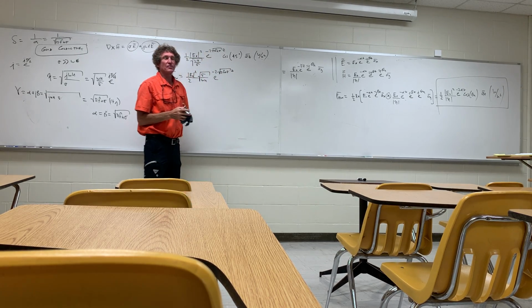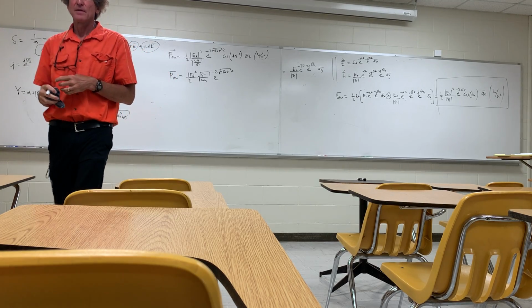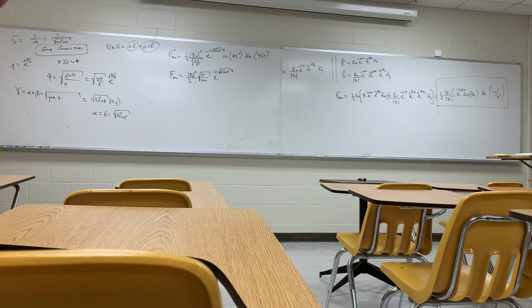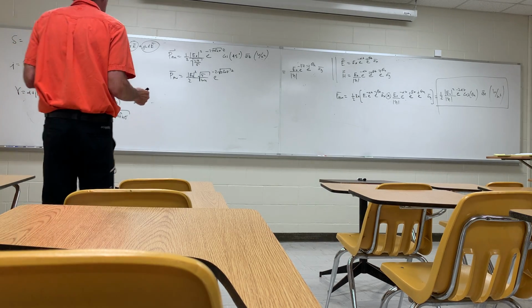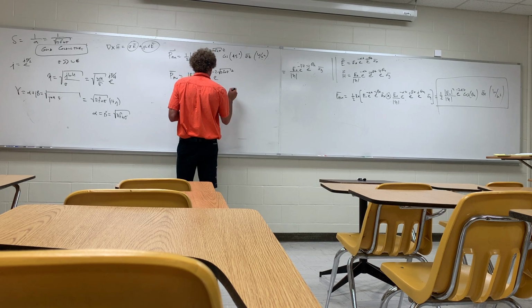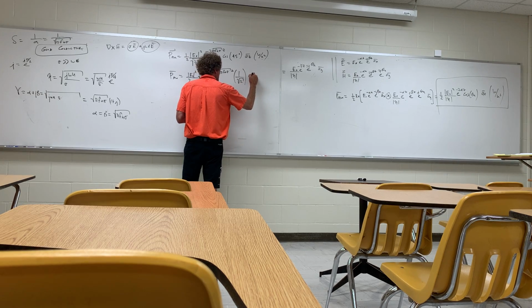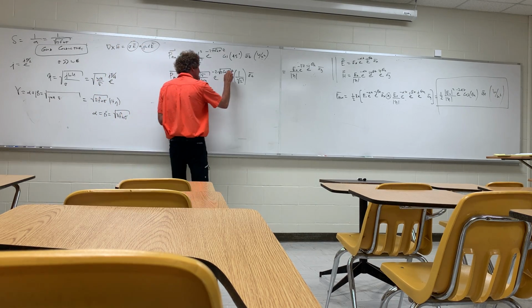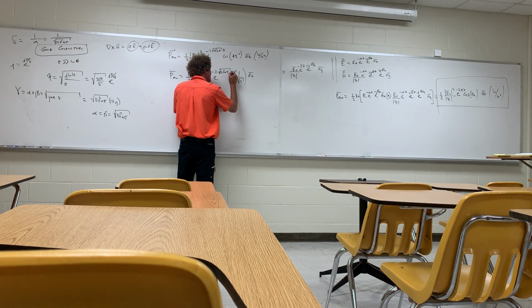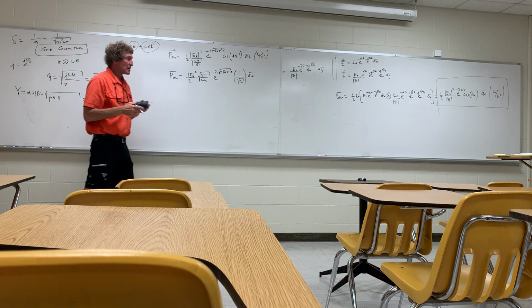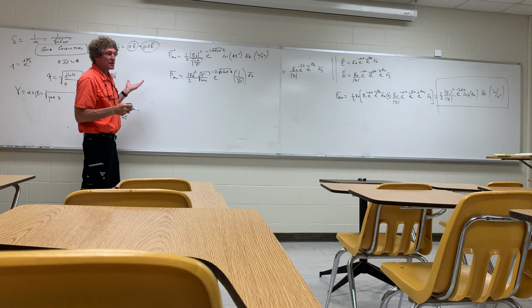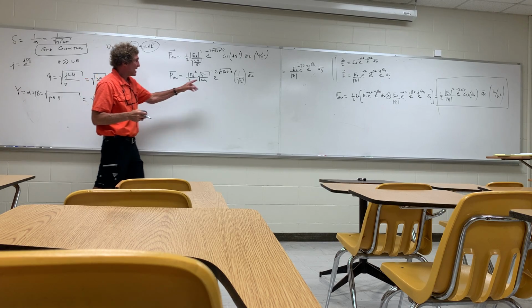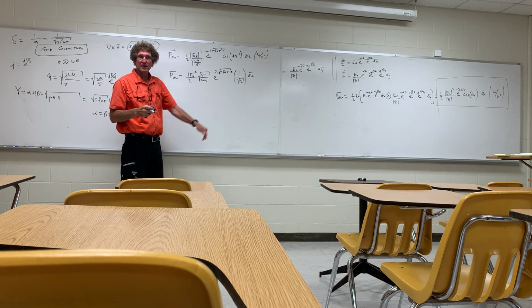And what is the cosine of 45 degrees mathematically? 1 over the square root of 2, that's a good way to write it. So I can simply take this thing and put this times 1 over the square root of 2 in the a_z direction. And that's power flow in a good conductor if it's flowing in the z direction. Now that's it. But you can plainly see that if you have power flow in a good conductor, this rapidly attenuates. It just basically goes to 0.